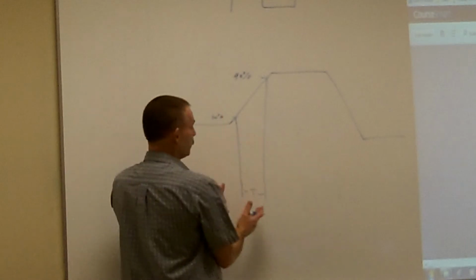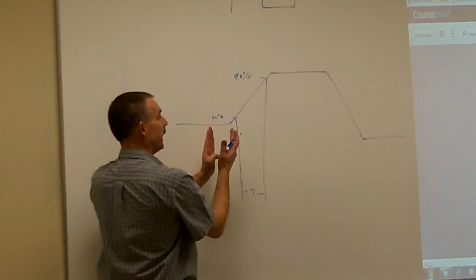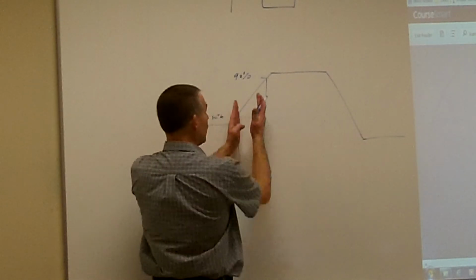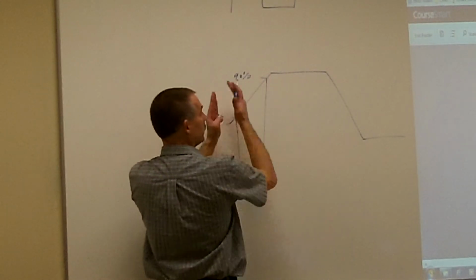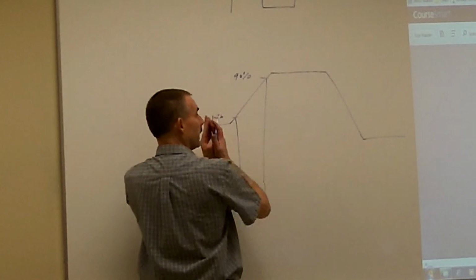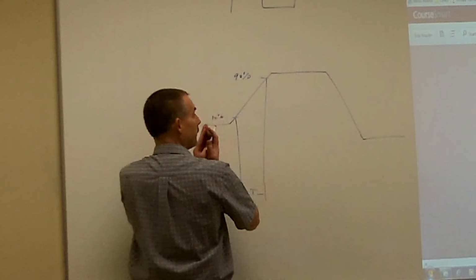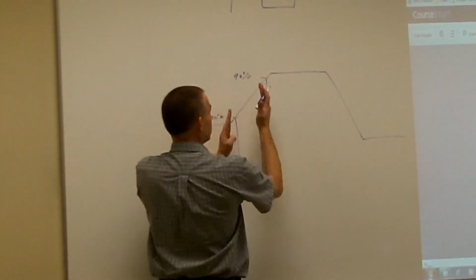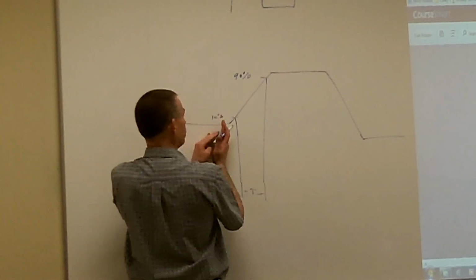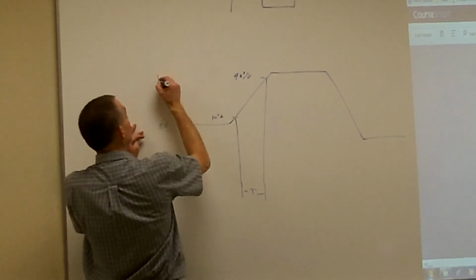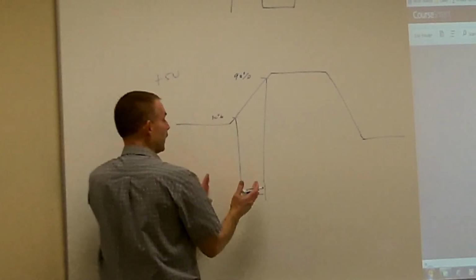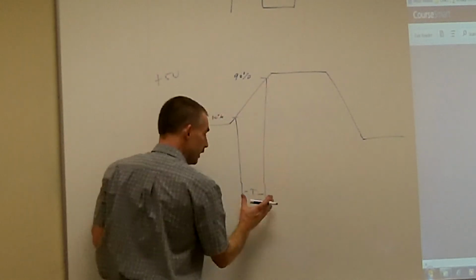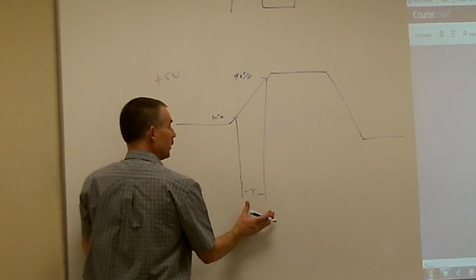And that's if we're doing something with very large amounts of data or transferring stuff very quickly. If this time takes way too long, we could literally miss a signal, or we could have so much propagation delay, because by the time I get through thousands of digital circuits, all this stuff adds up, because it's not going to turn on instantaneously. It doesn't go from 0 volts to plus 5 volts instantaneously. It takes a certain amount of time to transition from 0 volts to plus 5 volts. And that little time there is our rise time.